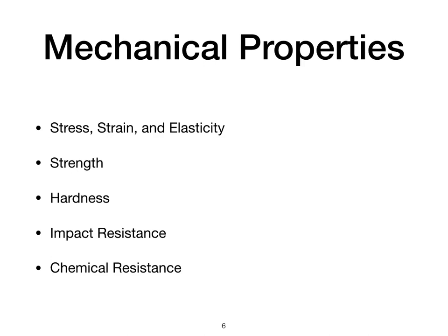Mechanical properties. Stress, strain and elastic property. You may be surprised to learn that glass is an elastic material on the atomic level, which is very astonishing. This means that under stress, glass will deform due to the nature of its atomic bonding structure. However, this change is not permanent, and when the stress is removed, the glass reverts to its original form. The stress on a glass is defined by force applied to a unit area.